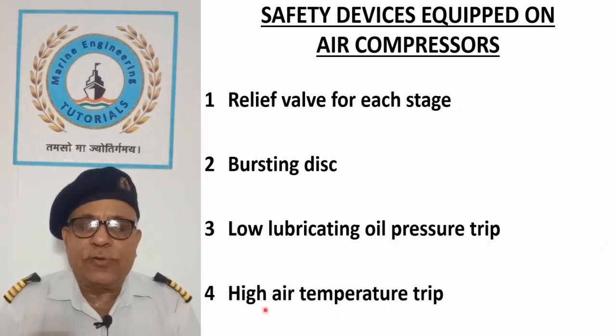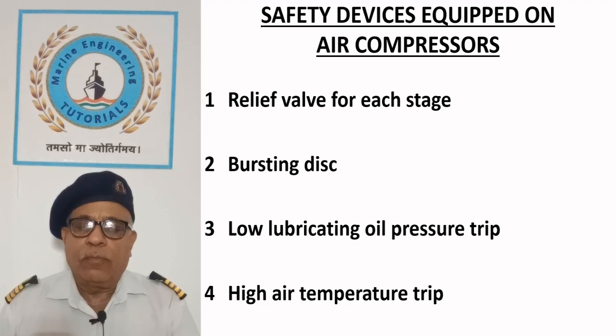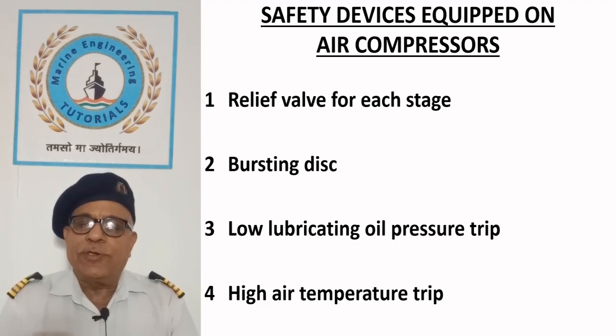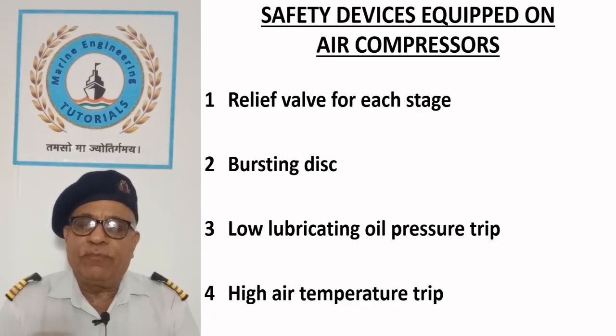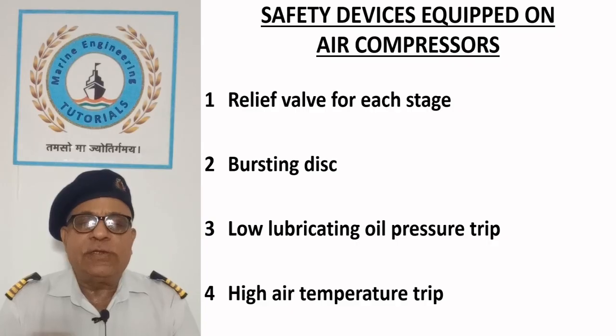High air temperature trip. High air temperature trip is equipped on the delivery air pipe. It is usually set to trip the compressor at 65 degrees Celsius to prevent the seizure of piston in the liner due to failure of cooling water.